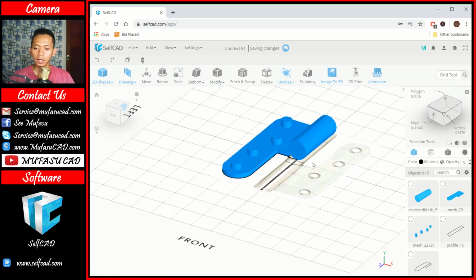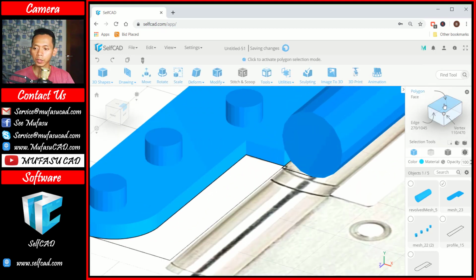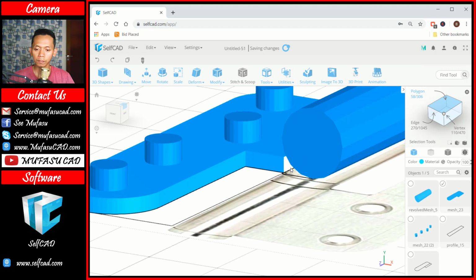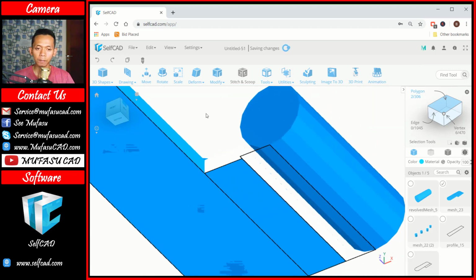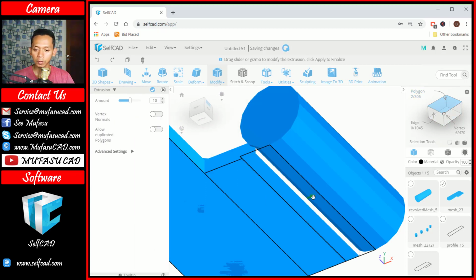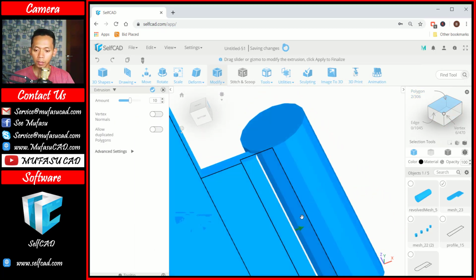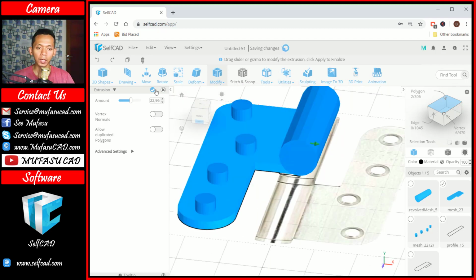I will select this object and then I will use a polygon option. You can click at this face and next we can use extrusion to extrude this face. Okay, you can click modify, click extrusion. We extrude in the green axis. Okay, you can click in here green axis, move to this point. Next you can click OK to apply.